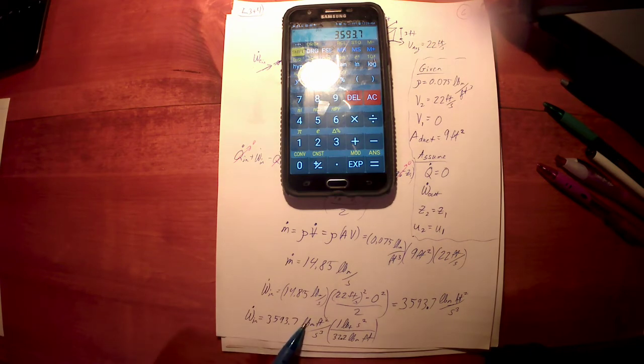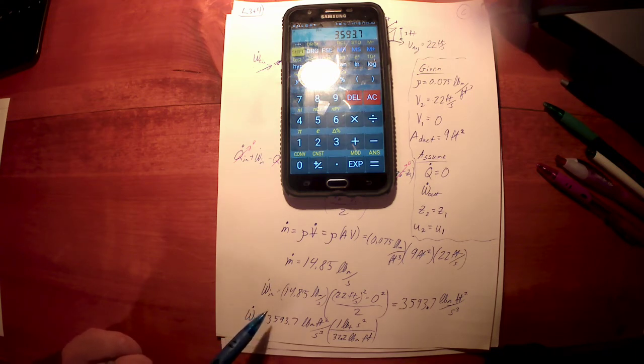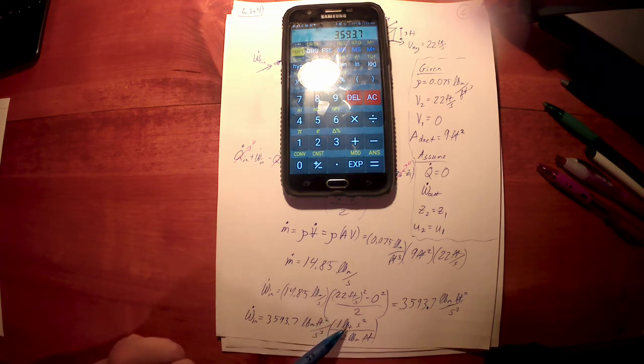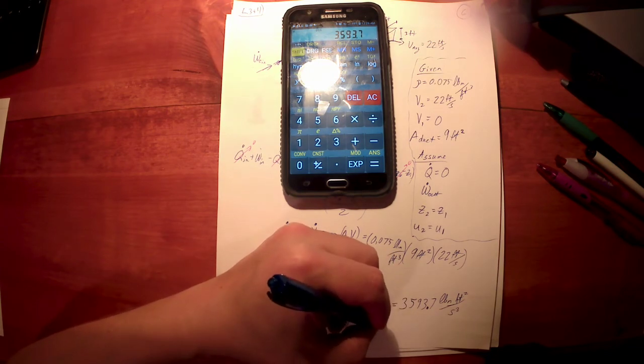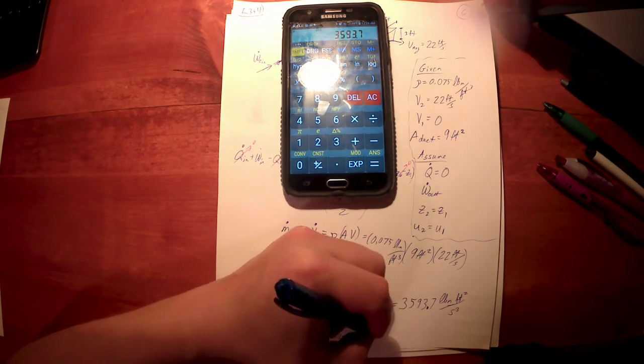Anytime I've got pound mass and I want to go to pound force, this works. Why would I want to go to pound force? Well, if I've got mass, I want power. That's force, that's energy per time. That's force times distance per time. So I want to go from mass to force. And this is going to leave me with pound force, feet per second. That's force times distance per time. So if I've got force times distance on top per time, I should be able to get that to power.